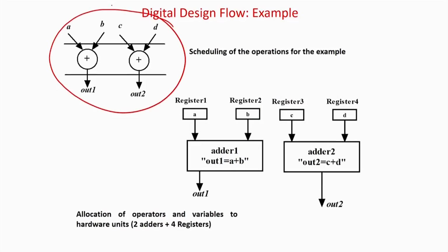This is actually called scheduling. High level synthesis first involves the scheduling process, where you have to do A plus B and C plus D. Do I need the answer in one step or in 2 steps? If you need the answer in one step, then both adders have to be scheduled in step 1, because there is no dependency. Now fine, this is one schedule.